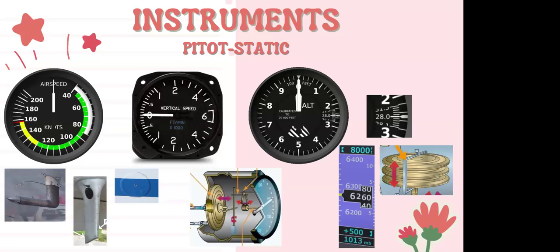Well, that's a big difference, right? If we don't reset our altimeter setting, our little Kollsman window, we're going to have a highly inaccurate altitude reading, which can be dangerous for us, dangerous for other people, and just overall inconvenient.